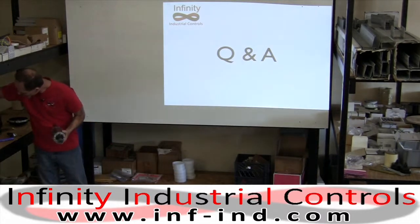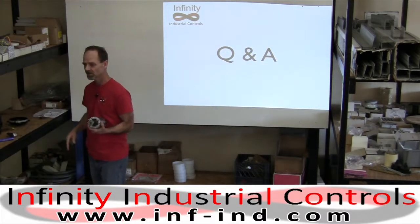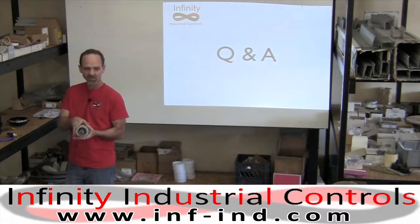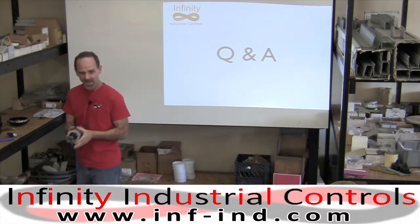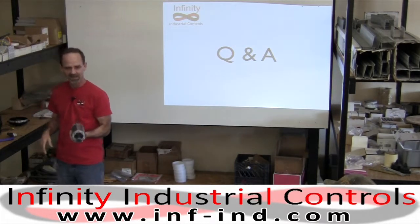A motor that has 4 sets of poles runs at synchronous speed of 1800 RPM. But in order for this to generate torque, it has to slip past those magnetic fields and develop its own magnetic field, so that it has something to push against. So they call that slip. So they usually run about 1750, something like that.